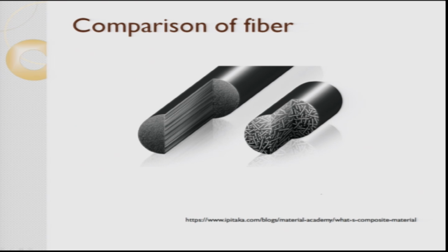For more understanding from the visualization point of view, you can see this is a continuous fiber oriented along the pipe. This is a chopped strand. So, the continuous fiber is broken into several small fibers, short fibers. If you look at it, this does not follow any uniform pattern. A fiber is cut into several small pieces, and they are all mixed and blended inside the polymer, and it is extruded here. This figure is only to give you a comparison between continuous and chopped strand mats, which are cut into pieces and then mixed with the polymer.